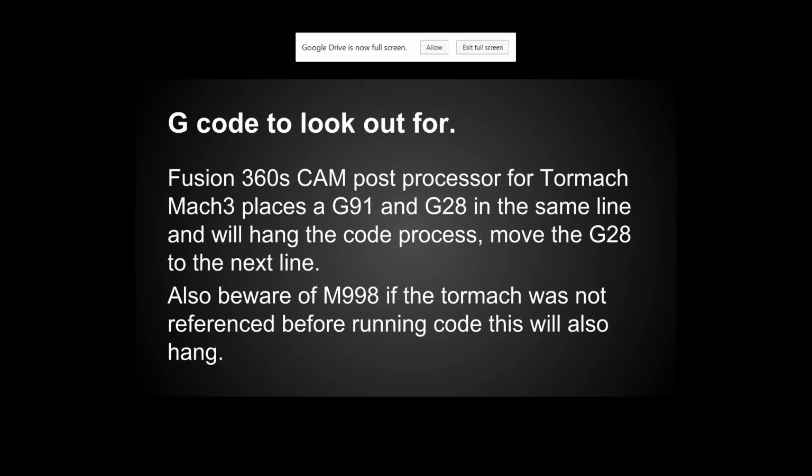Okay, here's what I found, and I'd just like you to comment if you had experience with it. Alex and I used the generic G-code and then found that it didn't have the ShopBot header in it. Yes, ShopBot uses very specialized versions of G-code. Typically, the only way you can get that header if you need it is to copy it out of an already existing set of ShopBot code. That's what we used to do. Yeah, instead of using F commands for feed rate, it uses an M3, which in normal Fanuc generic G-code would be spindle start clockwise.